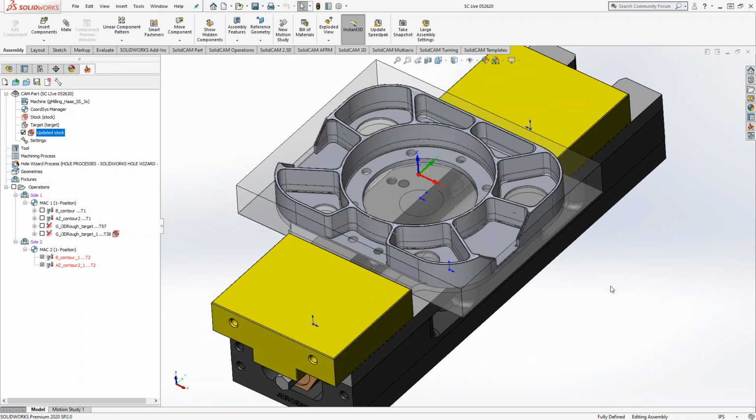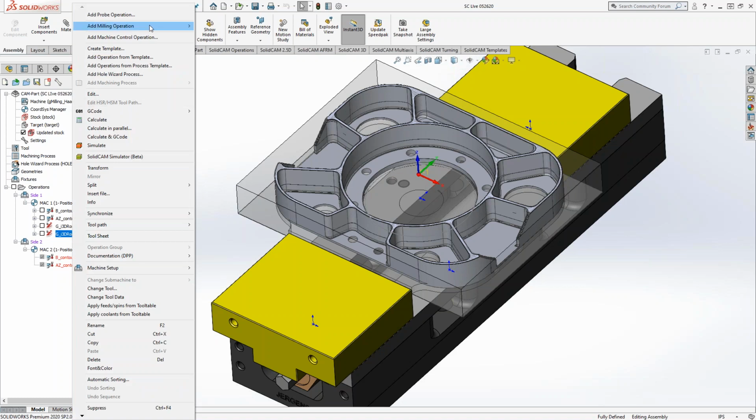So with a large part like this, again, if you just have the 2.5D package, you can do pocket and profile. Again, you choose your individual geometries, feeds and speeds for your finishing tool and all that. If you have the 3D package, you've got a lot of different options to work with. For a part like this, I'm thinking, what do you think, Kevin? Maybe HSM? Yeah, that's probably how I would tackle the next one.